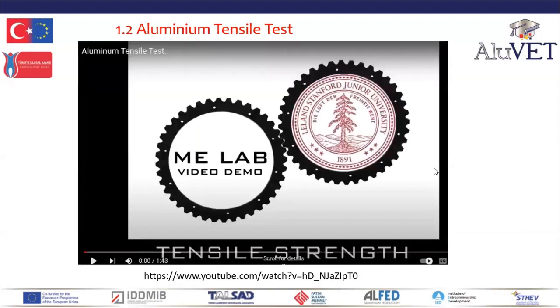I have a little video now of a tensile test. The video plots the progress of a tensile test. Initially, we measure elastic linear movement of the load against stretch. Then we shall see the yield point and the transition from elastic to plastic behavior. And finally, we will observe the maximum breaking load, maximum breaking stress.